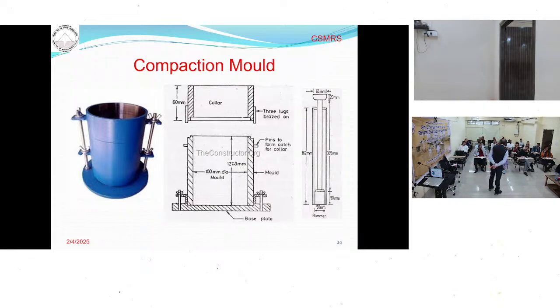If you are using non-plastic soil or sandy soil, it should be around 8 to 10 or 12 percent generally. But in case of the plastic soil, it will vary from 30% to 50%. So first of all, see what kind of soil it is. Depending upon that soil, we add some water. Suppose we are talking about plastic soil, so we will start around 8%. At 8% moisture content, mix it thoroughly and keep it for some time.